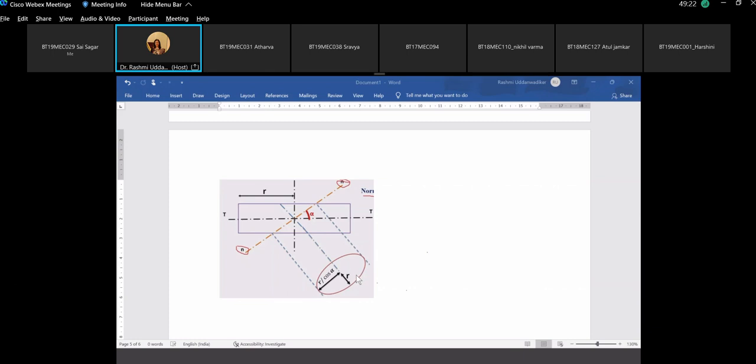This is an ellipse, and its major axis would be, if this is r and this angle is alpha, r upon cos alpha. The pitch circle radius is r, or d by 2. If I take its minor axis, this is Re, and I draw a circle with this minor axis as my radius, that is, a circle with radius equal to the radius of the minor axis of the ellipse, which is obtained by cutting the pitch circle with its normal plane.